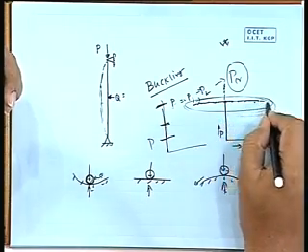So if you apply a load beyond the critical load, buckling will be there. There will be excessive deformation, so large strain, and the material will start yielding. Finally it will be material failure and entire collapse will be generated, but the failure will initiate with the buckling of the member. The value of P will keep decreasing for the extent of buckling that is taking place. Here the load will be constant, after that it may be like this.